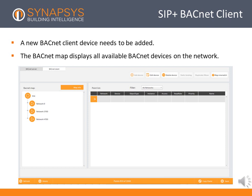Adding the BACnet client will open the ability to create new points in the table. The BACnet Map tool will also be made available. The map will enable a full search of the visible BACnet network, showing all devices and points available to be polled by the SIP+. To discover devices, highlight the site by clicking the label and press the refresh button. The Map Info tab can be used to show the status of the search. When all devices have been mapped, highlight the device required to learn the points available.